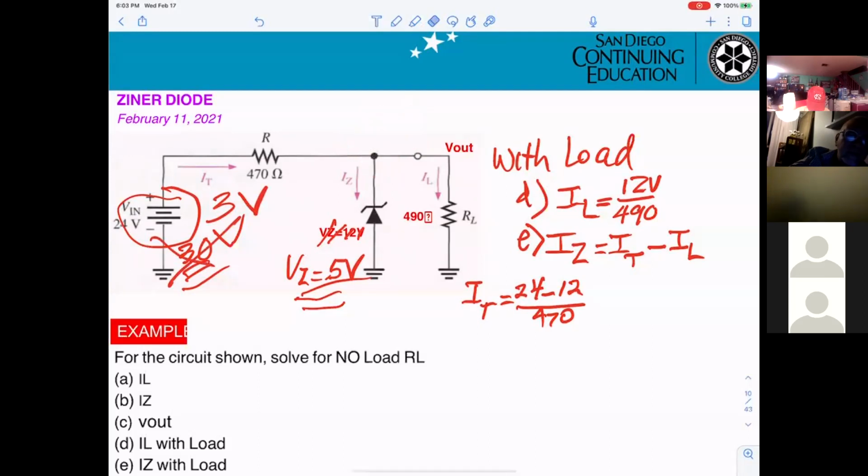There is one exception to that. If the source voltage is above the Zener voltage, if the load resistance is low enough, then the voltage divider effect will keep the output voltage below the Zener voltage. So that's one complication. So basically, the Zener diode is just like a fixed regulator of that voltage at that point. Right. Okay. But only for voltages above the Zener voltage. Right. So it's not broken if it's below it.